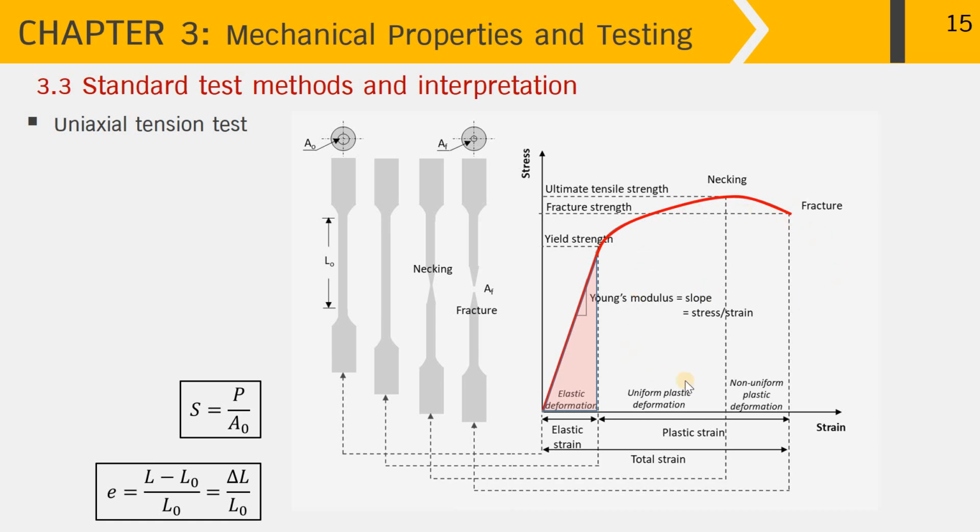And now let's analyze a little bit on the areas under this graph beyond the elastic limit. This area shows the energy consumed by the specimen during strain hardening and necking through fracture. And this area is huge for metal. It means that metal can be deformed over a range of deformation, giving a variety of shapes.